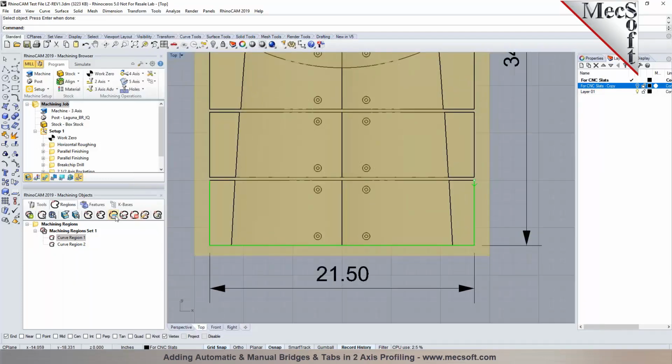And now I can go ahead and pick bridge point locations where I want my bridge points to be placed. We have what's called manual bridge points, and I can select locations. I can say one of my bridge points to be in the midpoint of this line, over here, over here. I can do the same. I can select this one here, pick bridge point locations, manual bridge points, place one right here, one over here, one over here. If I want to move a bridge point, I can just select this here, and click on edit bridge points in selection, and I can basically drag and drop it. Right, so you have the ability to drag and drop your bridge points.